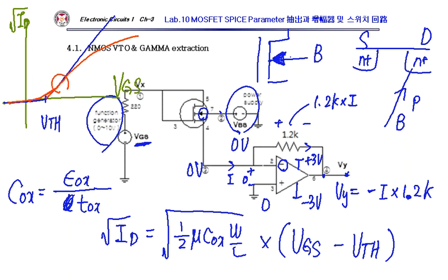So you need the operating region with the highest slope to find the threshold voltage. This mobility is reduced as the gate voltage is increased. Okay, question? No?